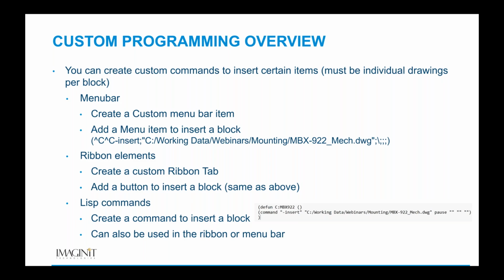Okay, so good question, Brian. I have done a bit of VBA with Excel. I know AutoCAD also has VBA, which is a separate download. Can I have a VBA macro as part of the block, so when I insert the block, the VBA macro runs? No. You can have the VBA macro insert the block and then do whatever you need to the block afterwards, but you'd have to run it all via the VBA macro and insert the block using the VBA so you could continue the information or the VBA macro.